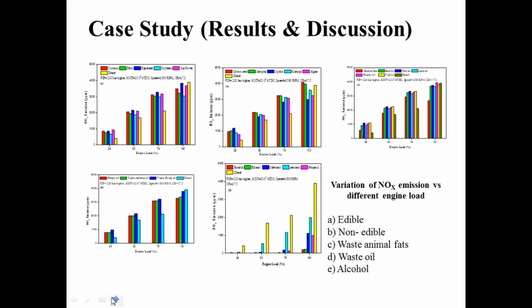It was observed at full load that the NOx was produced at some different values. The fraction of wet NOx in exhaust gas is lower by around 20% or maybe 21% for the soybean biodiesel.